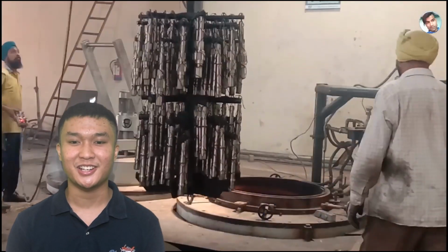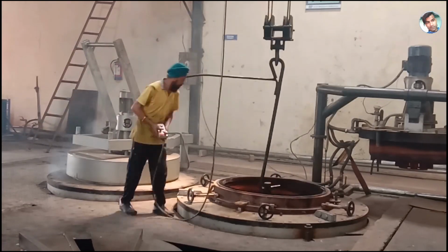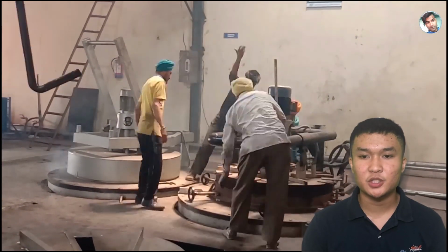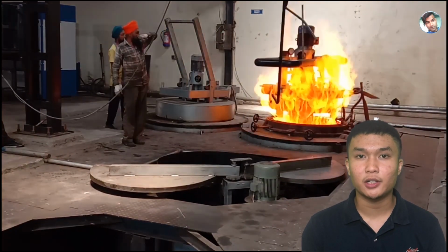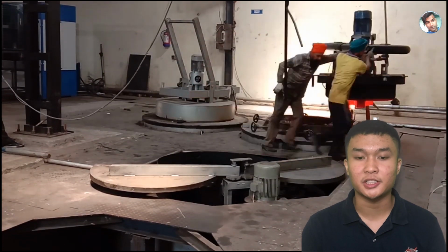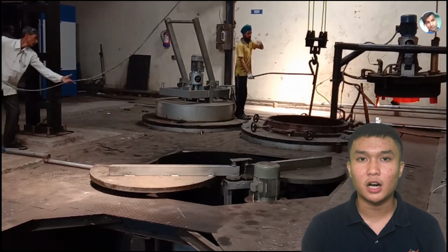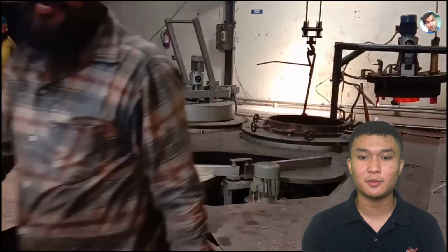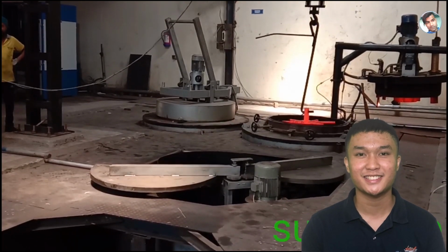A material rich in carbon is introduced into the furnace atmosphere. The carburizing atmosphere is produced by the use of various gases or by burning of oil, wood, or other materials. When the steel parts are heated in this atmosphere, carbon monoxide combines with gamma iron to produce practically the same result as those described under the pack carburizing process.